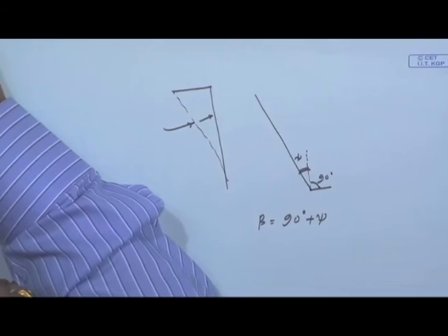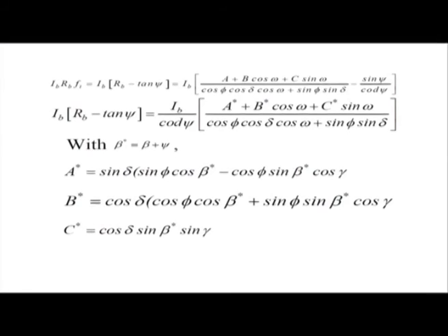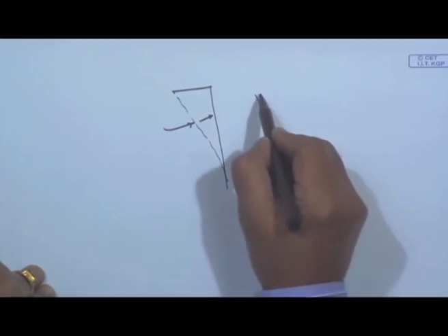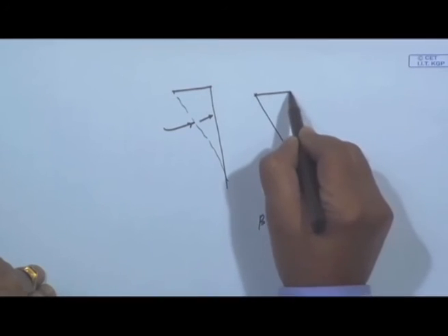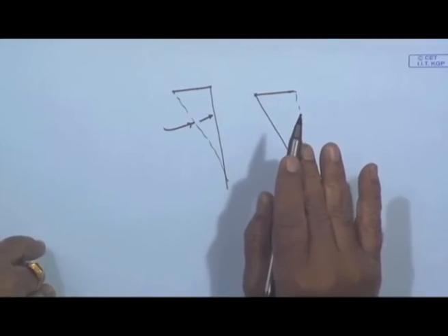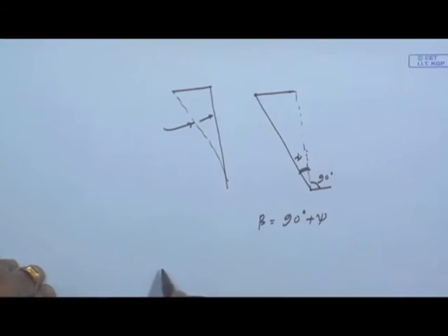So, if you want to calculate a monthly average daily radiation, or the Fi bar, without going through the Fi calculation, you just calculate the daily radiation or the monthly average daily radiation on the plane which joins the edge of the overhang to the base of the window. But this is under the assumption that the overhang is infinitely long.